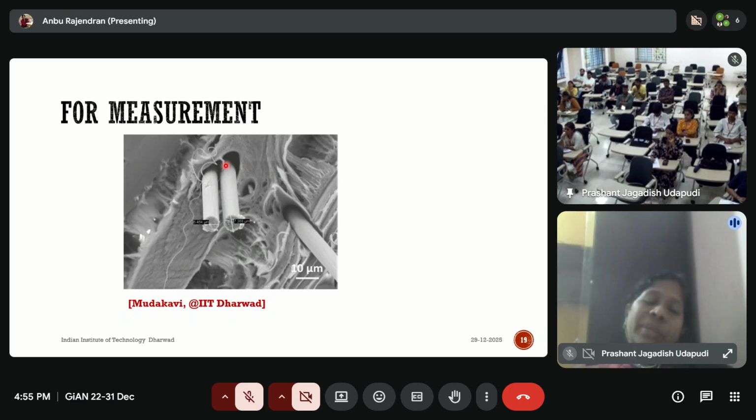The same thing is available even in optical, but very fine features cannot be seen at the macro level. Whatever is at a measurable level in the sample can be measured using the image analyzer software attached to the optical microscope. Even optical will provide the same facility for the same purpose. Only for fine details you cannot use optical. For that you can go for SEM.